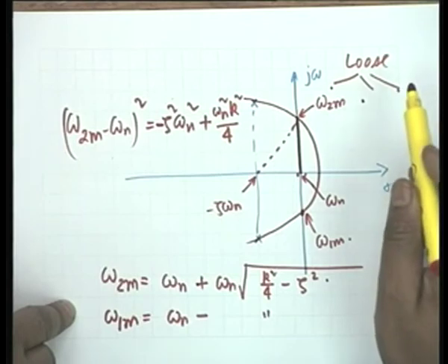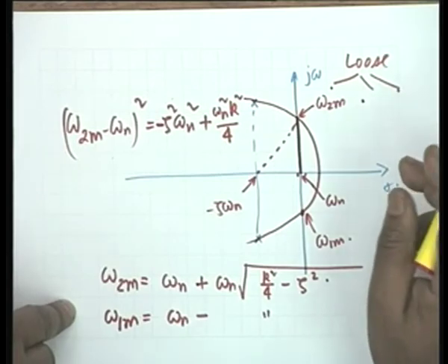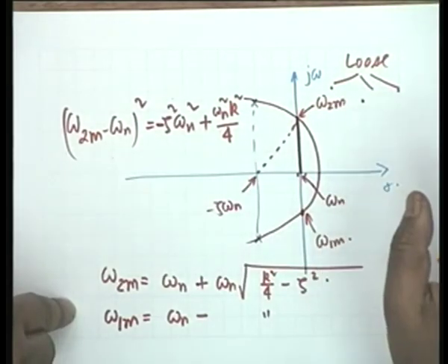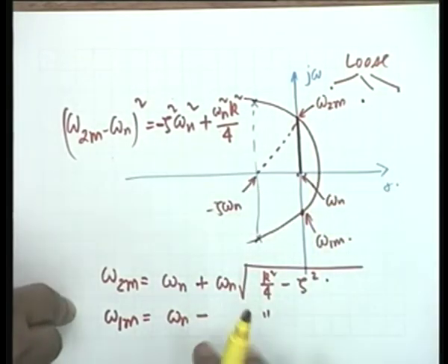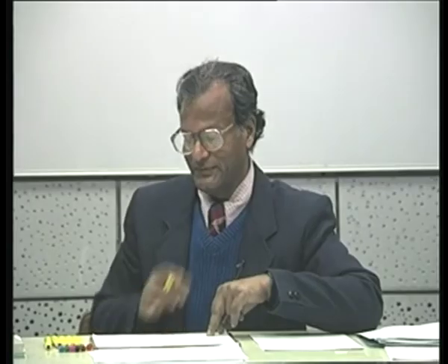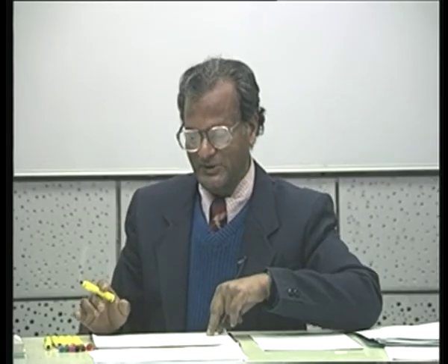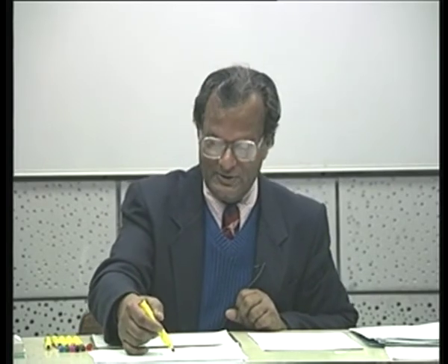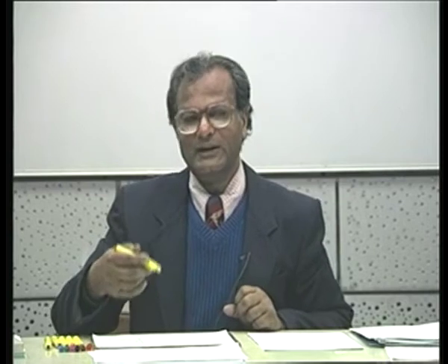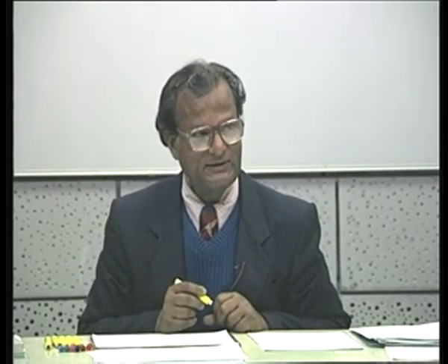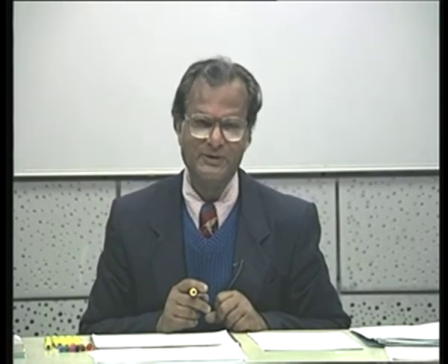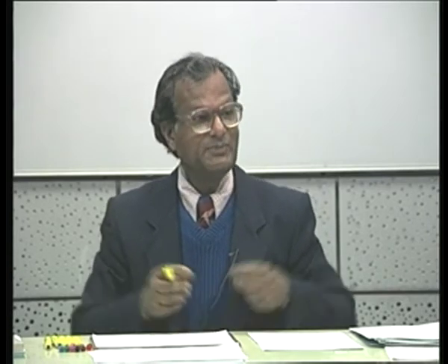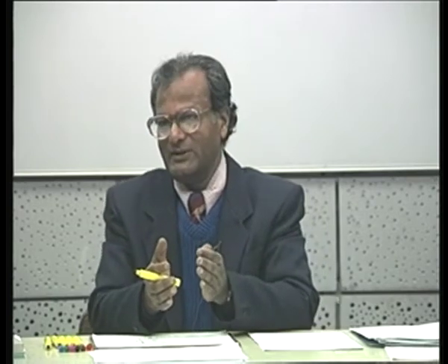Now over coupling may be increased to an extent that all these assumptions go down the drain. Then none of these expressions will be correct. Is that clear? If you bring them too close to each other, then there will be sharp peaking, but in between the dip will come so low that the circuit would be useless, and therefore these are to be decided from experimental considerations, that is by trial and error, by bringing them close together and so on.